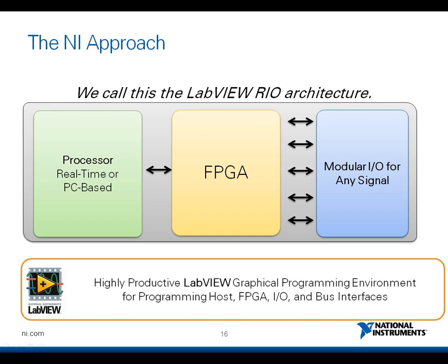Now the NI approach to solving these applications is to incorporate both an FPGA and a processor into a single device, where the FPGA is directly connected to modular I/O. This is what we call the LabVIEW RIO architecture. Now RIO stands for reconfigurable input-output. Then the LabVIEW graphical programming environment is used to design this entire system, and it includes built-in functions for handling I/O and bus interfaces, which provides you with maximum power and flexibility.